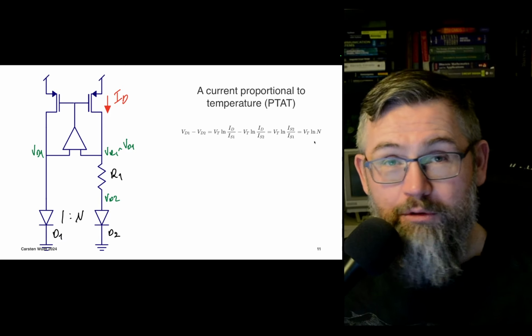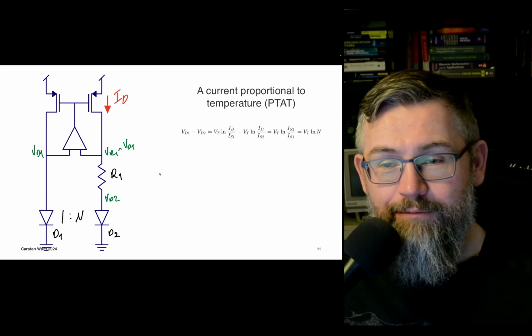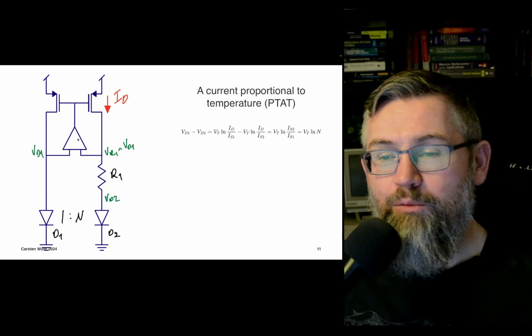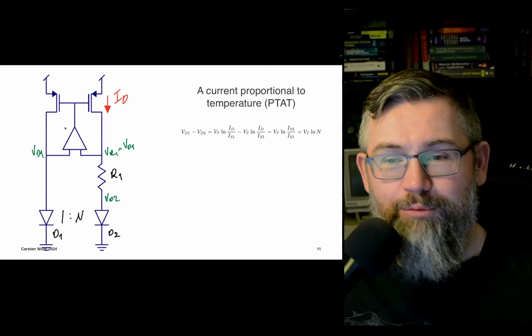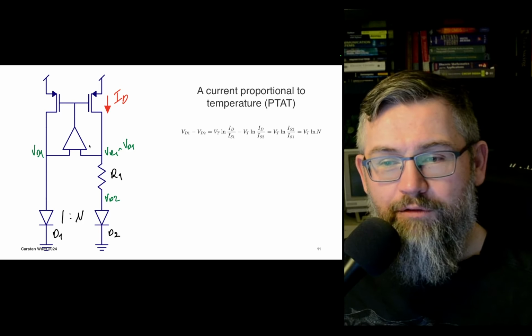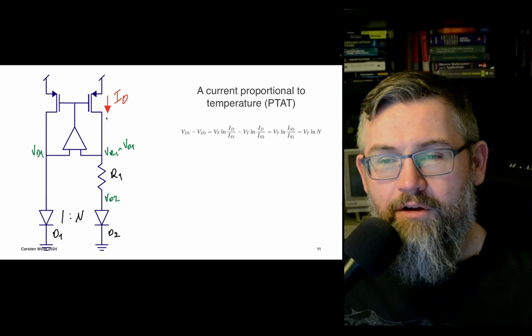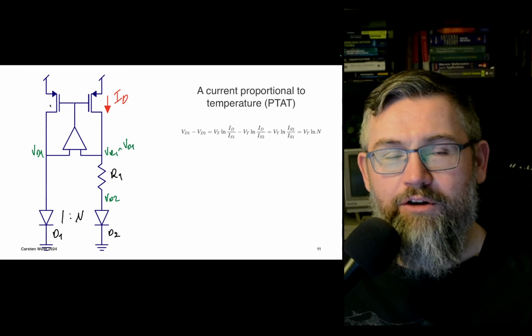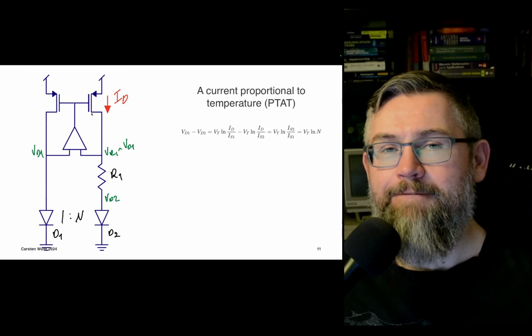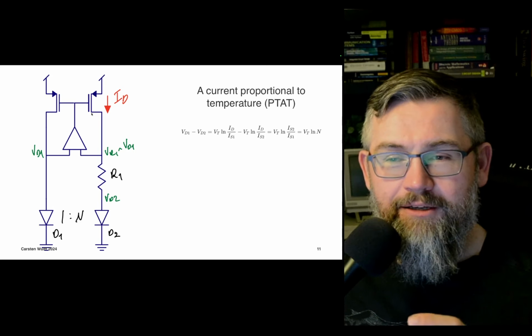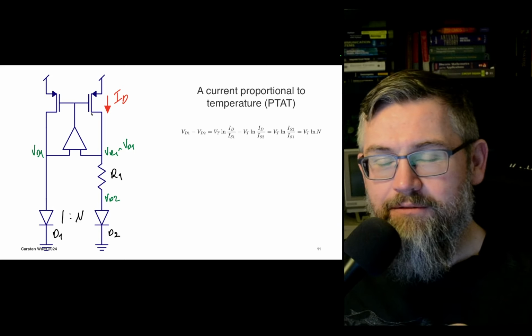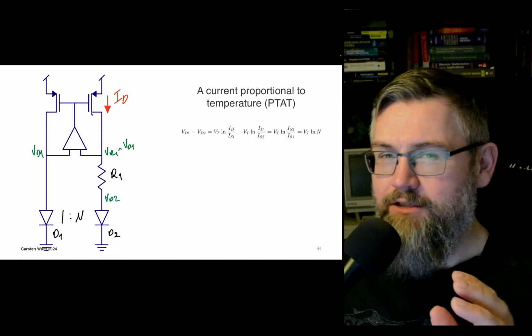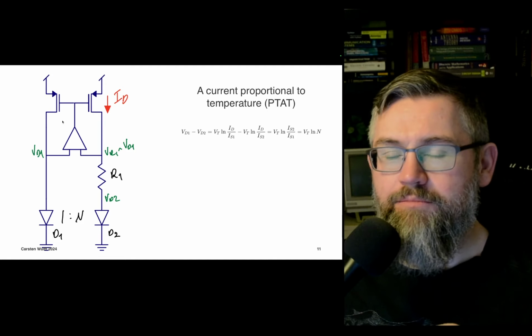It's not possible to have exactly the same voltage on both sides here. There will always be some remaining offset from the op-amp. The transistors in the current mirror will not match precisely. There will be matching issues there. There are techniques to address it, like dynamic element matching and so on.